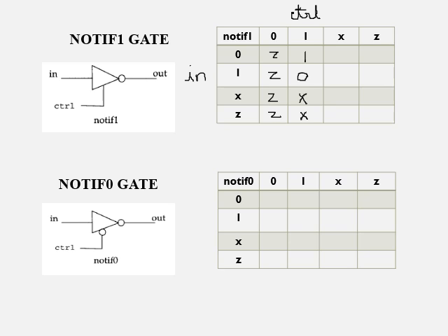So here for X and Z, we really don't know what the value is. It could be a low or it could be a high. So if it is an active signal and the input is 0, we would get an inverted 1, so H will be transmitted, and for a 1, it would be transmitting a weak low. And for remaining values it is unknown.